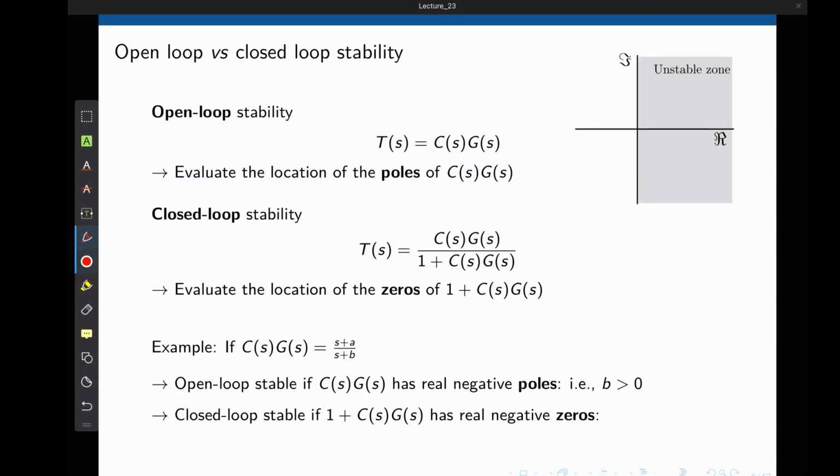Another important aspect of any system in the frequency domain is its stability. And the Nyquist stability criterion is one way to infer stability of a closed-loop system. The advantage compared to temporal domain techniques is that here we can determine the Bode plot based on experimental data, and based on the Bode plot infer the stability of that system if used in a unit feedback loop.